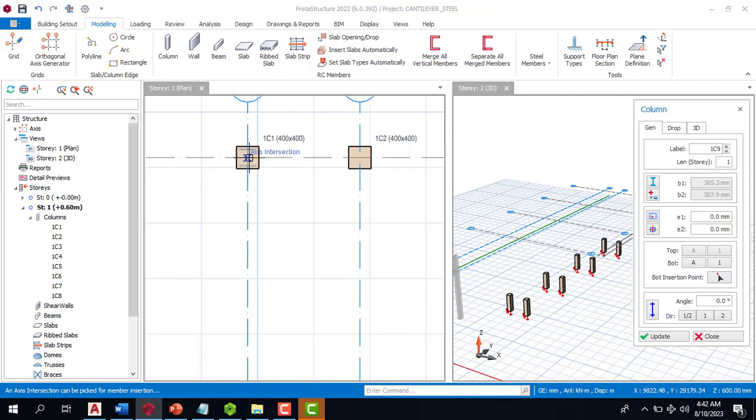Okay, so you already know some of these steel cross sections that will serve, so it spares you a lot of time, the time in which you will start going through changing your steel when it comes to checking for the utilization ratio and the slenderness ratio and all of that. Okay, so experience already helps you to spare a whole lot of time.